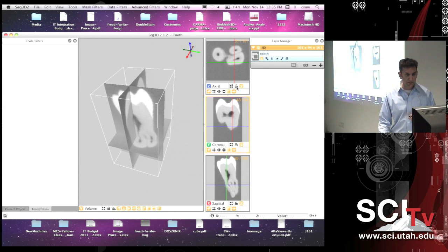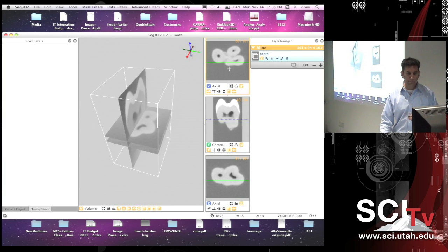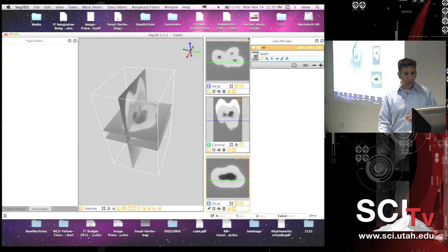Okay, this lock thing is perhaps worth noting. If I switch this to be another axial view, so here I have my two blue axial views, and I move one of them, and here I'm just using the scroll bar on my mouse, it can move independently of the other. If I go in and tell this view and this view to remain locked, now as I move through in one of them, the other one is staying at a fixed offset from it. So hopefully that's clear. Turn those off.